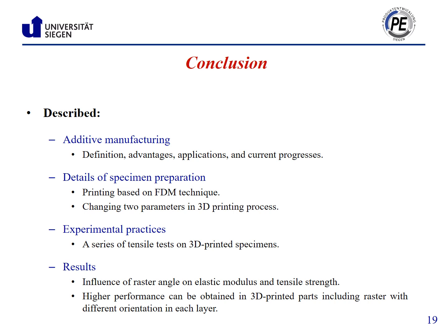and from these curves, we can directly see that both strength and stiffness depend on the raster orientation and printing speed. Particularly, it can be seen that the specimen with raster orientation of 0 degrees has the highest strength and stiffness. The obtained results showed that both parameters decrease with an increase in the raster angle. Moreover, we have performed fractography analysis and the obtained results are presented.